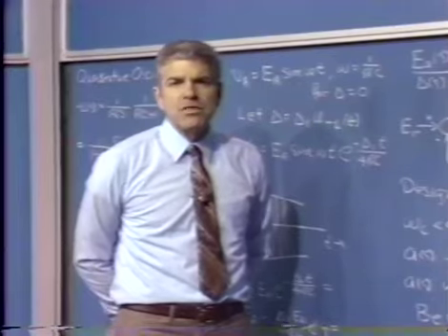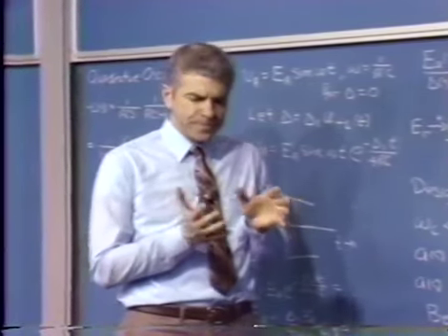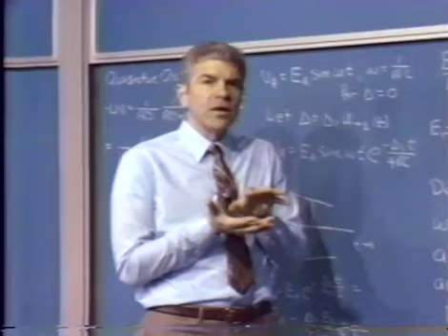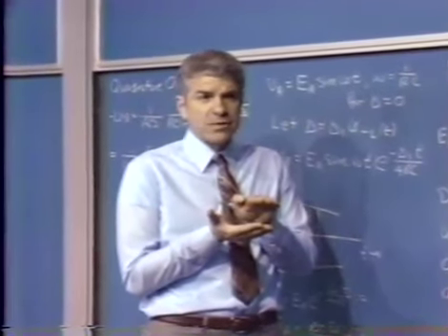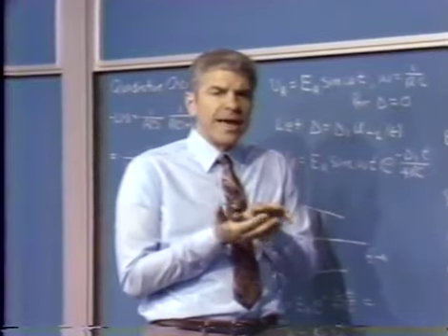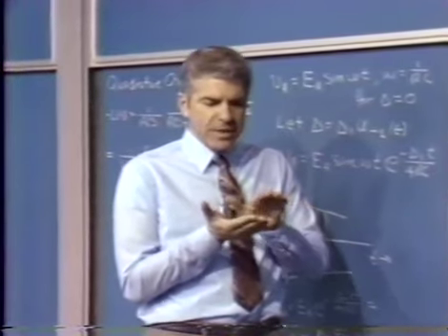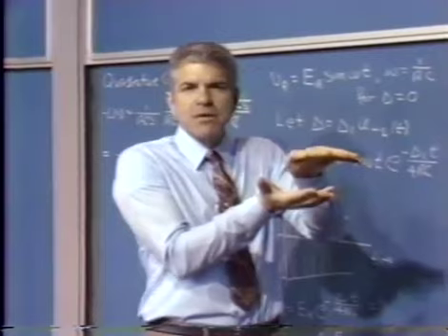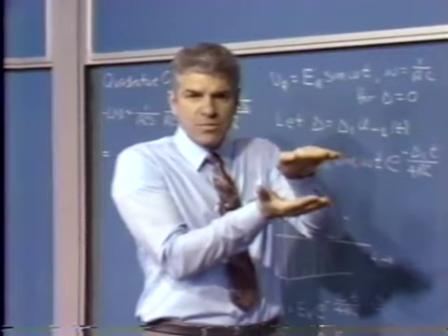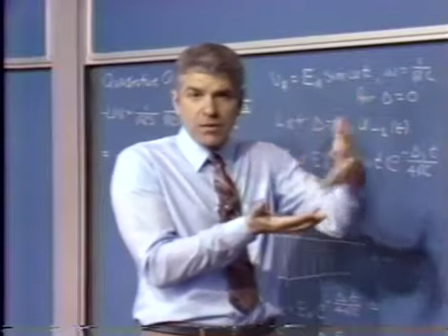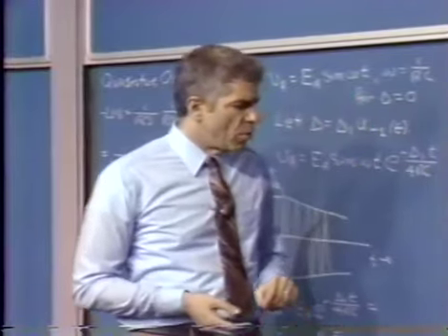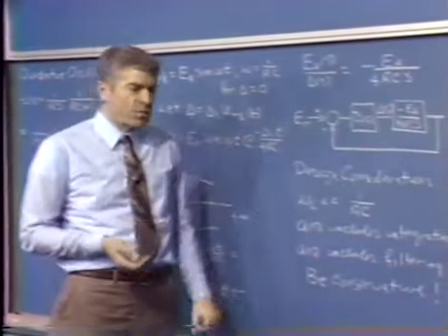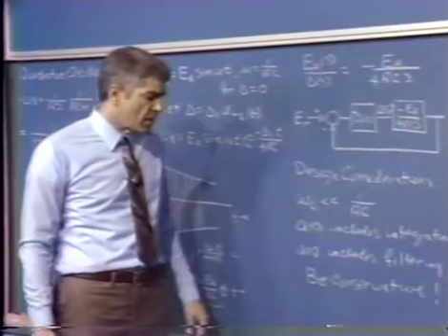And what we have to do is filter that, because if we think about the overall loop, we're going to apply some measure of the envelope or the error to our control element, to a field effect transistor, possibly if we use that as the control element. And while I think the analysis is difficult, probably beyond my capability, modulating the control element at some high frequency can't possibly be good. We'd like to have the control element have a fixed value of resistance over an entire cycle or many cycles of oscillation. So what we'd like to do is include a lot of filtering so that this high frequency trash that's a consequence of our envelope detection gets filtered out to insignificant levels.